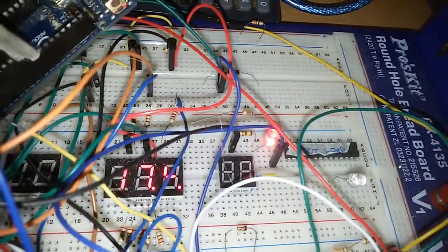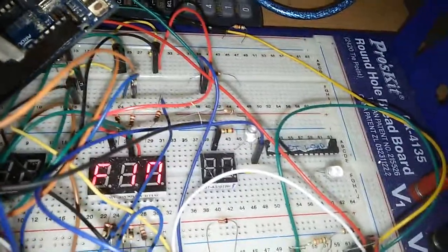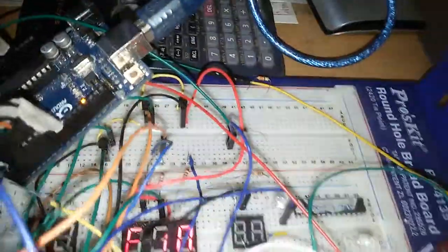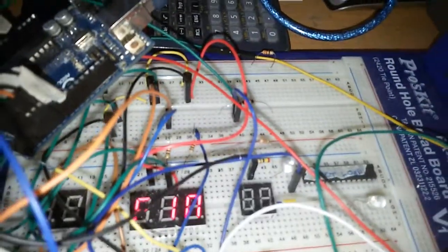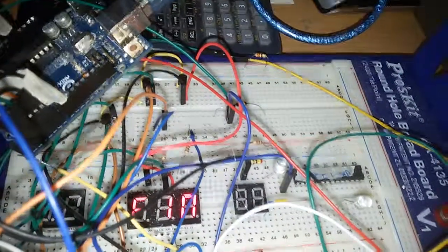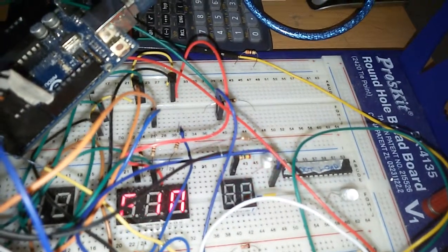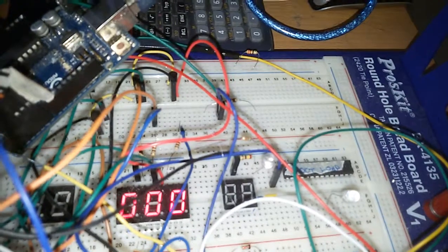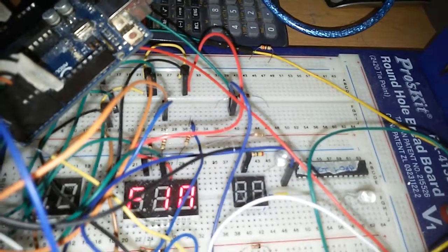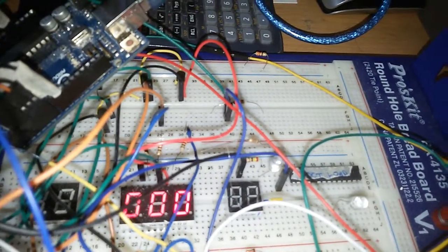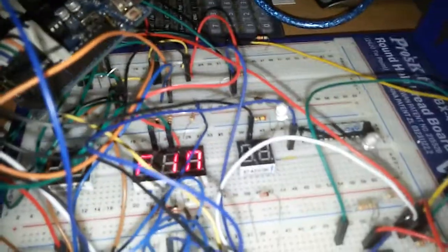So at 17, the PWM output is reduced, and when it reaches 18.5, it will display fin, that is finish. So it will keep on strobing. When it is already full, it will keep on strobing from finish to 17, something like that. So when it's above this one, it will become 0. It will display 0. So that's it. Okay. Thank you.